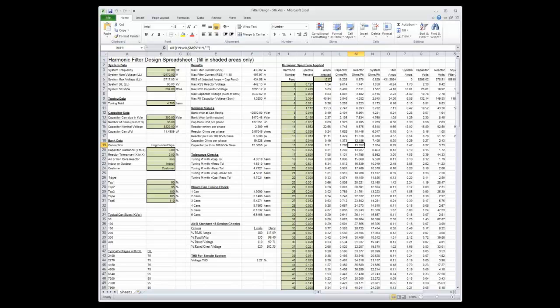And so, remember, for every capacitor that you put on the bus, as you're changing it, if you're switching on more capacitance, you'll find that your resonant point is shifting all the time. So if you're going to do a staged bank of any kind, believe it or not, you're going to really need to test it for each one of those stages. If you do a staged bank with filters, you have to have a set of 3 reactors for every single one of those stages. So your cost is going to be going up dramatically.